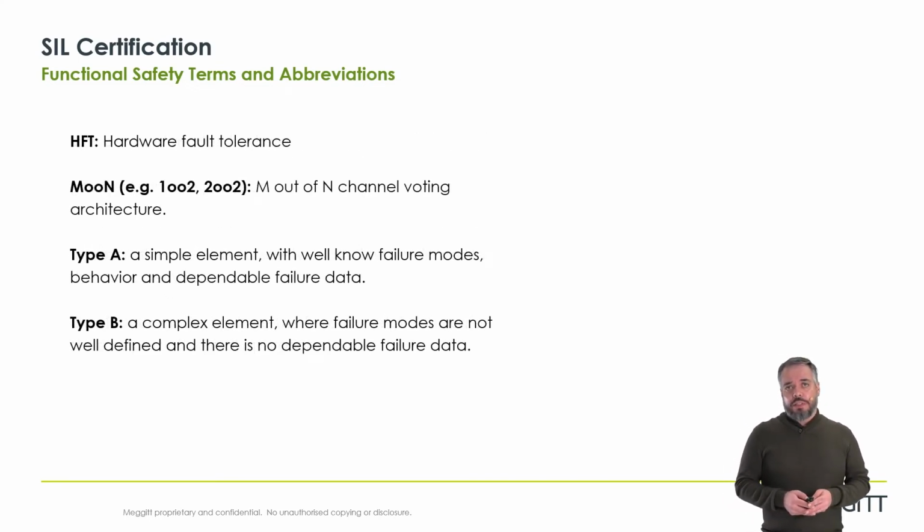Hardware fault tolerance, HFT, simply means how many hardware faults the system can tolerate while still being able to execute its safety function.